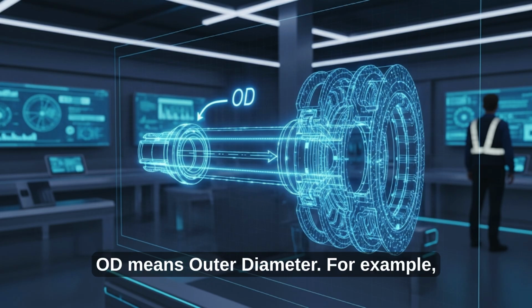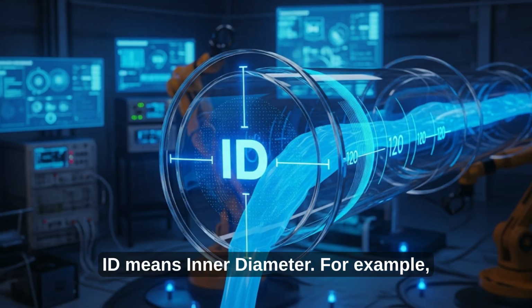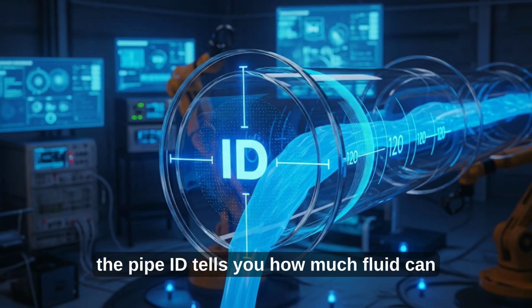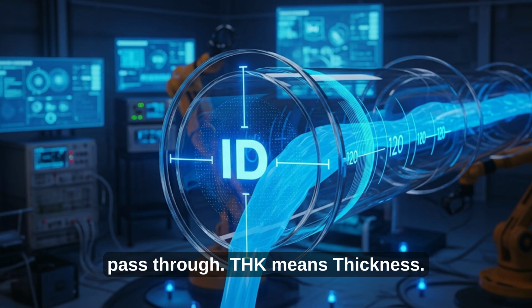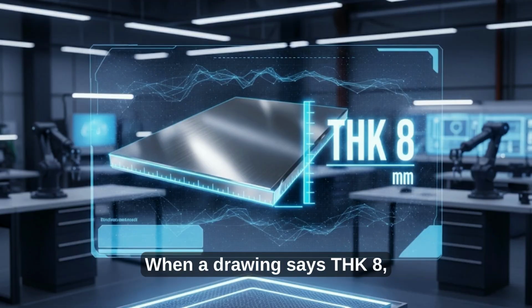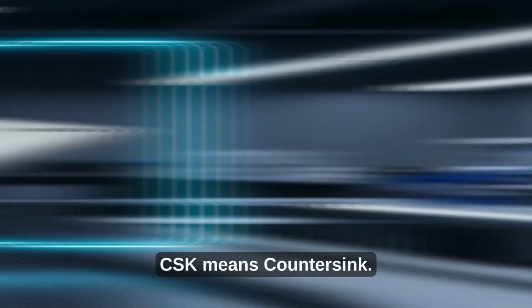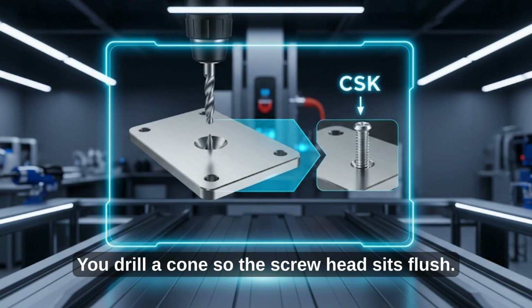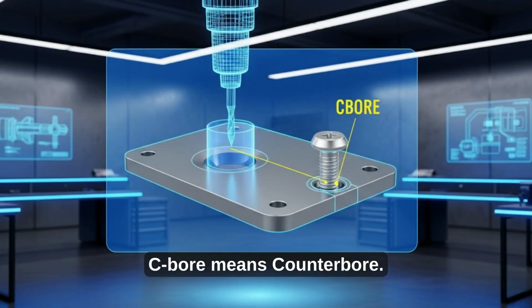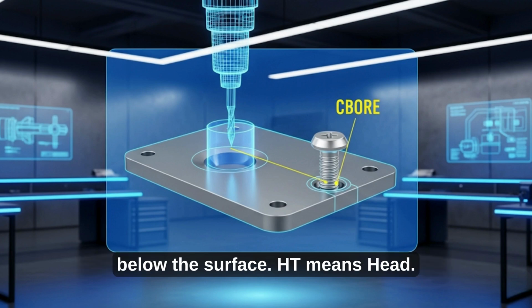OD means outer diameter. For example, the shaft OD must fit inside the bearing. ID means inner diameter. For example, the pipe ID tells you how much fluid can pass through. THK means thickness. When a drawing says THK 8, you know the plate thickness is 8 mm. CSK means countersink. You drill a cone so the screw head sits flush. C-bore means counterbore. You drill a flat pocket so the screw head sits below the surface.